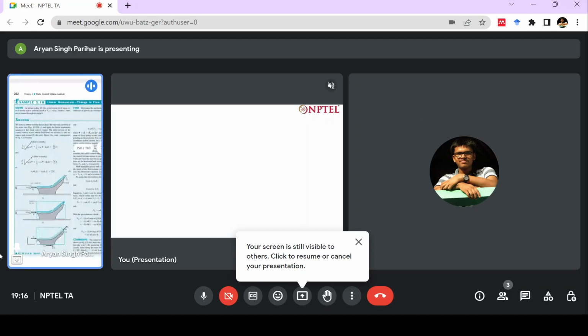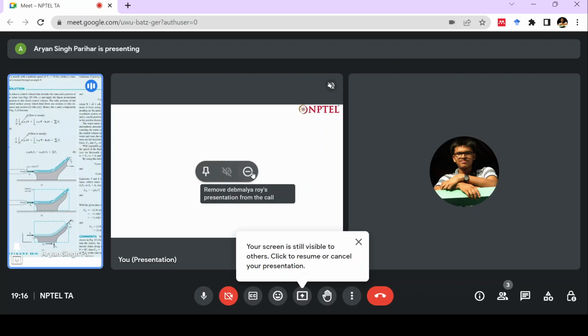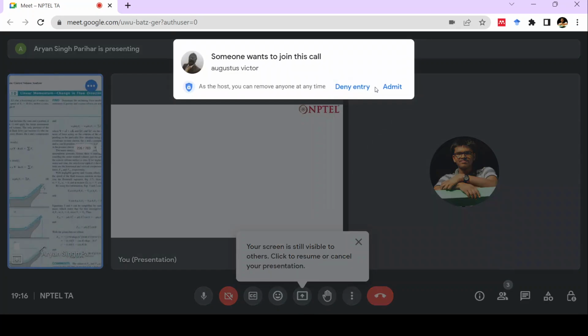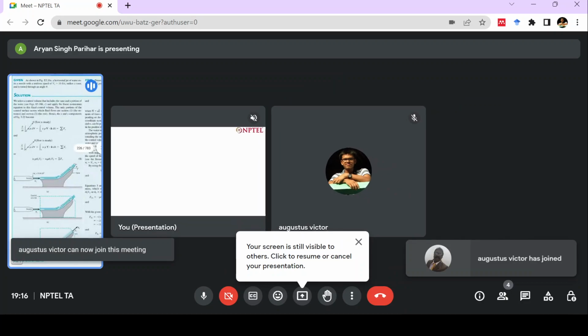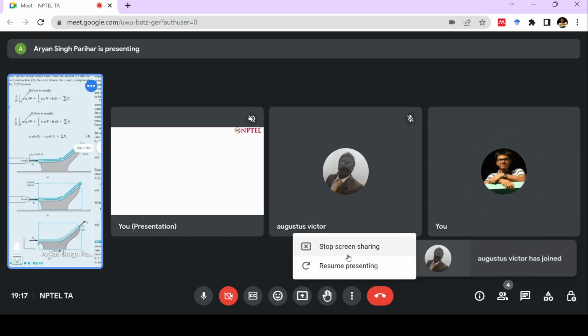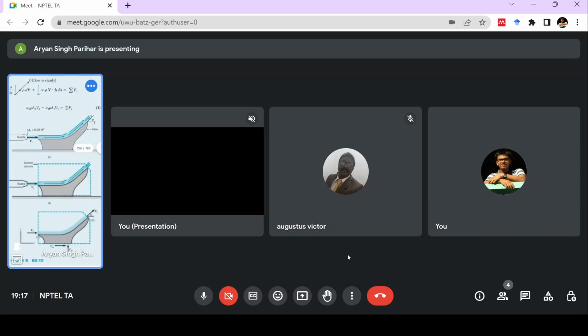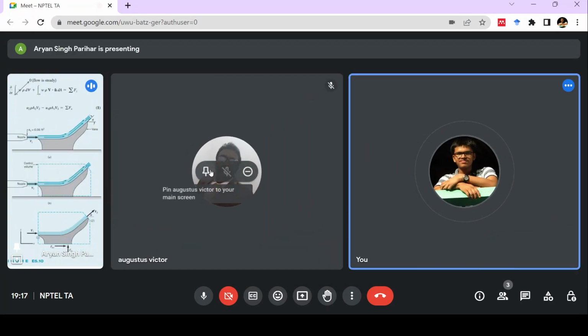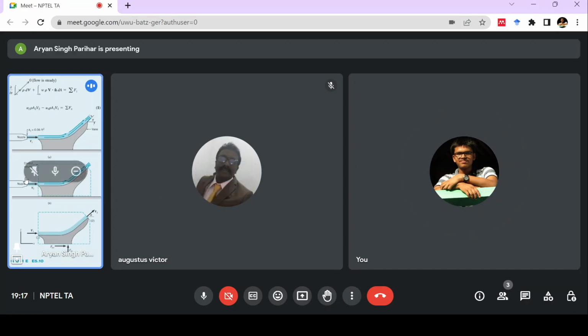Sir, here is a problem of a horizontal jet of water which exits a nozzle. It strikes a vane and is turned through an angle theta. The vane is kept stationary, and it is asked to find the force needed to hold that vane stationary. Here the control volume has been chosen like that, you can see by these dotted lines. In the lower portion it cuts through that solid vane, and in the rest of the portion it is surrounded by fluid.